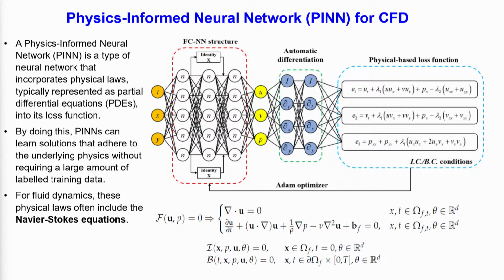So, this is an example of what you do for Navier-Stokes equation. What is written here is a bit of mathematical notation, because usually mathematicians will work on this, but just take it physically: the capital F, the set of PDEs which form the backbone of this physics informed neural network, are the continuity and the momentum equations. Usually you take everything on one side and set the right hand side equal to 0, because your error is measured by deviation from 0, which is called the residual.